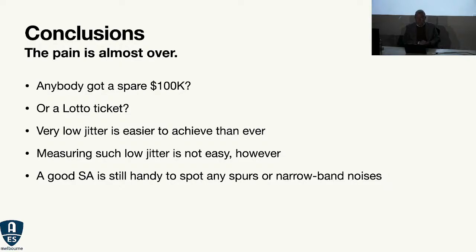But it's good to have a good spectrum analyzer around, because you can look for all kinds of noises, spurs, narrowband stuff. I've spent an unbelievable amount of my time chasing little birdies around to find out where they're from and escort them out. Because until you get those clocks clean, you don't know what you have with your audio.